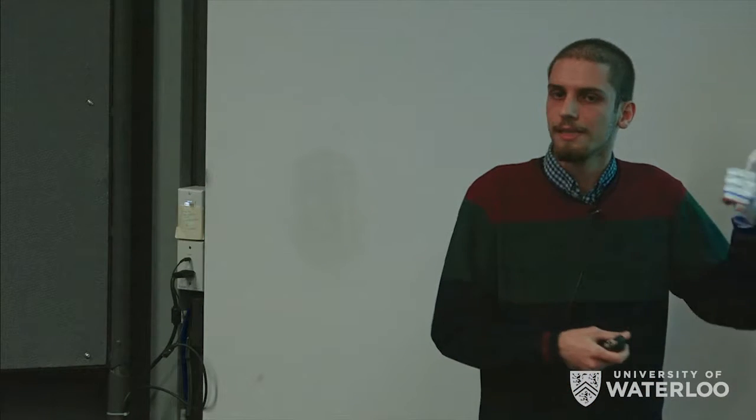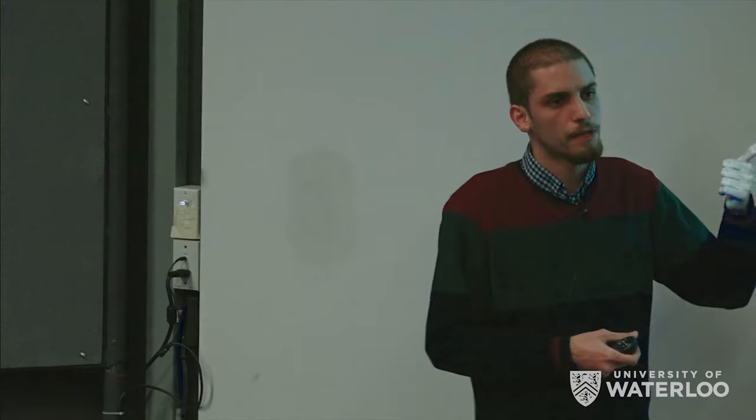So definitely it matters what kind of roof we are looking at. In case of salt as the roof, for the modeling of the roof stability we should use those creep models that we generate for the shrinkage of the cavern. In case of an elastic roof, the Voussoir beam is one of the models that we can use.